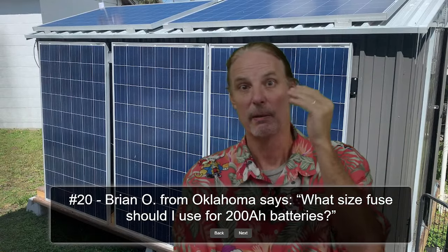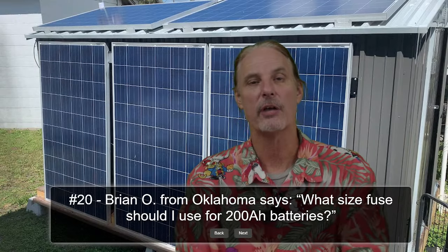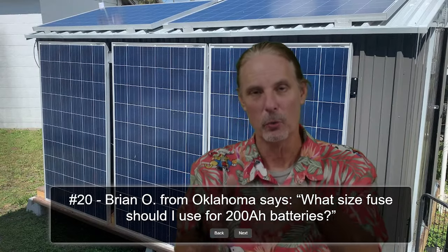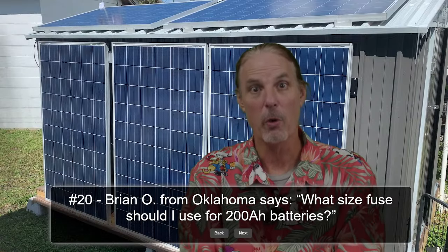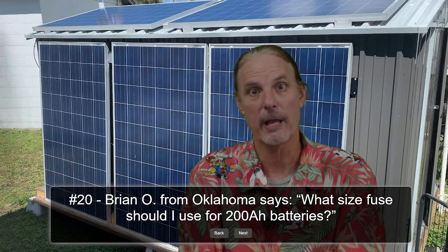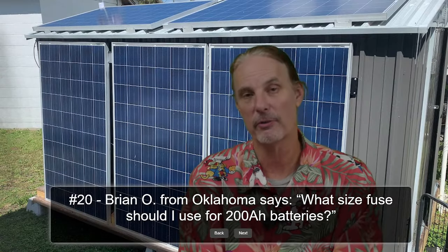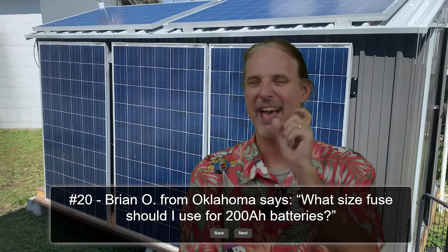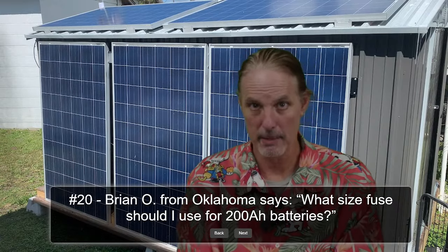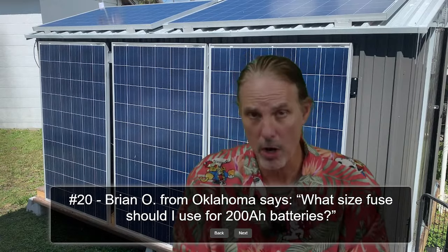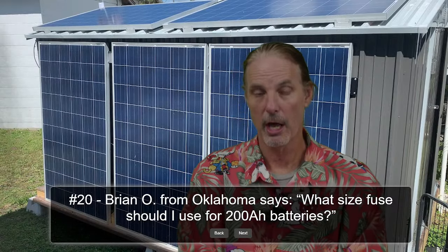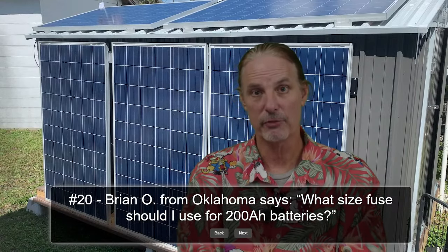I had 100 amp batteries. I assumed that two of them, one could go off, leaving me with 200 amp maximum pull, so I put in a 250 amp fuse. If you have a 100 amp BMS and you only have one, then you will want to do 20% of that, being a 120 amp fuse. And that would prevent it from overcharge there.